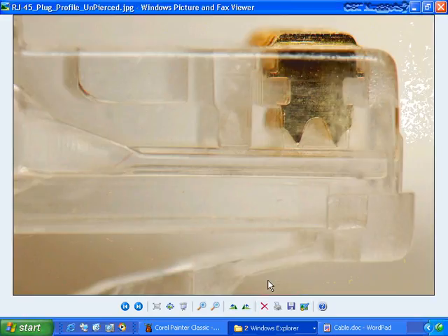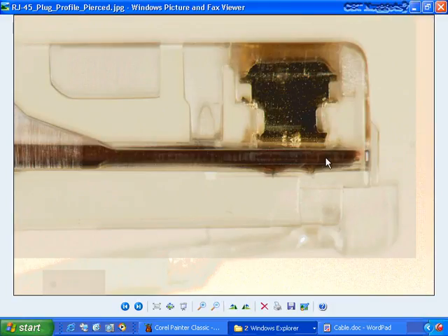And then here's a magnified side view of that jack, and notice that we have these taps on each one of these plungers that appear inside of that jack. What happens is you put this then into that crimper, and when you depress it down, it has a mating that appears right here above each one of these plungers that pushes it down into the cable. And then here's another view of it where you can see that these plungers have gone in and made contact with the inside of that cable.